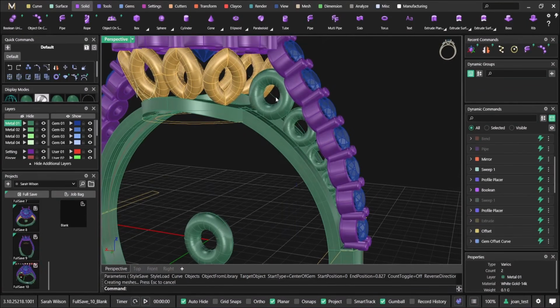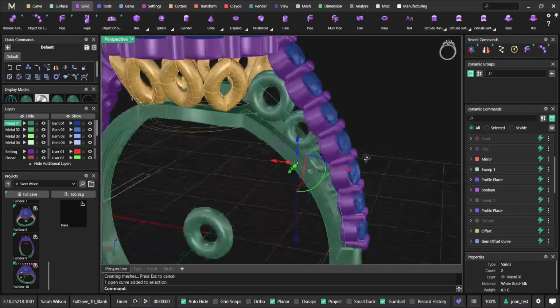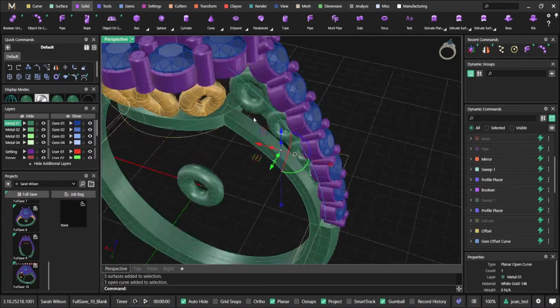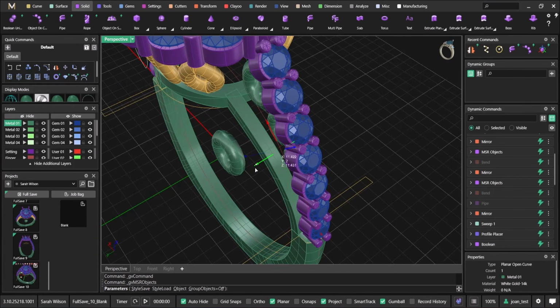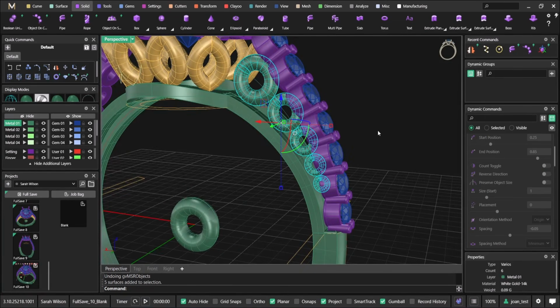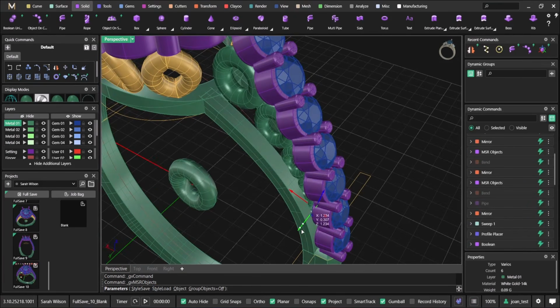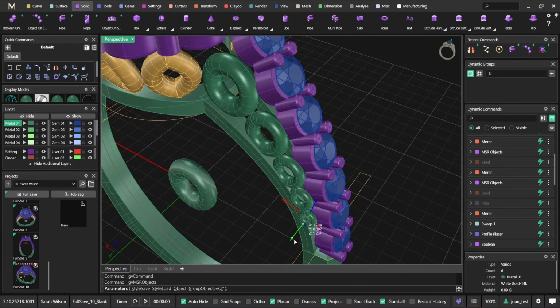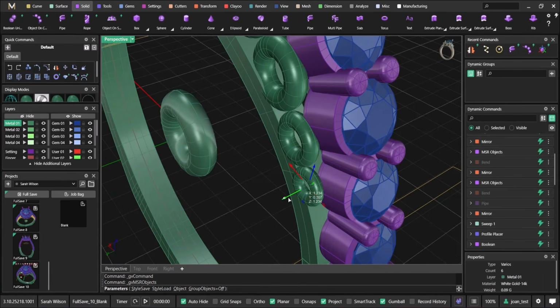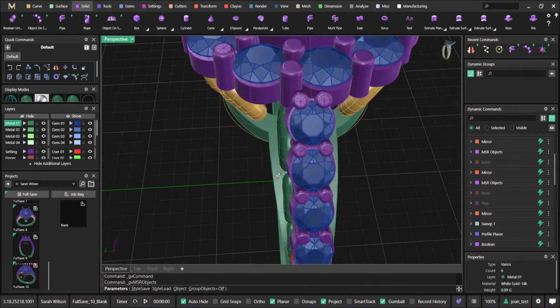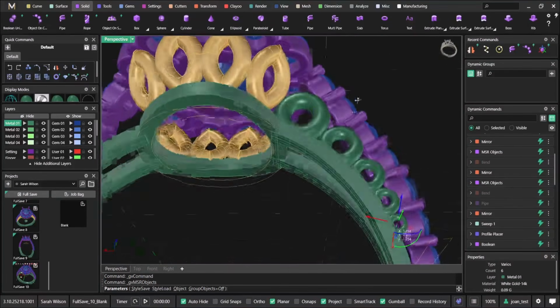As you can see now, the curve is in the middle. I obviously don't want that. And I want to keep things parametric. So I have different options. I can pick this line and use MSR objects, as we've seen before. Oh, that's not going to work because I need to pick this. So MSR objects and move it like this. Okay. But as you can see, this is going straight and the bridge is not straight. So I need to do something.